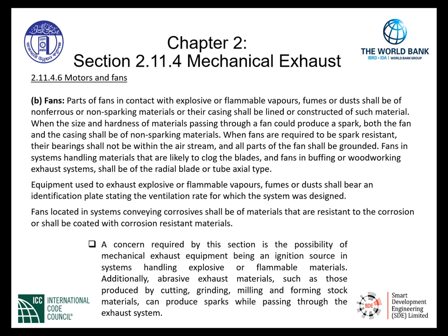Additionally, we read that abrasive exhaust materials, such as those produced by cutting, maybe grinding, milling, and forming stock materials, can produce sparks while passing through the exhaust system. This section is given to us for specific requirements regarding fans and parts of fans regarding this environment.